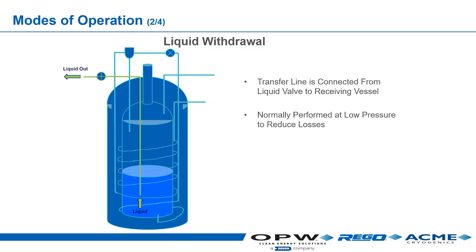But if you have a bulk tank, like the 6,000 gallon bulk tank outside, and all of a sudden there's a valve that goes bad and you have to drain that tank to fix the valve, you then have to pull that liquid out, which means the pressure in the container has to be higher to receive it. Wherever the liquid wants to go, the source that's pushing has to push the liquid out. It's got to be at a higher pressure.